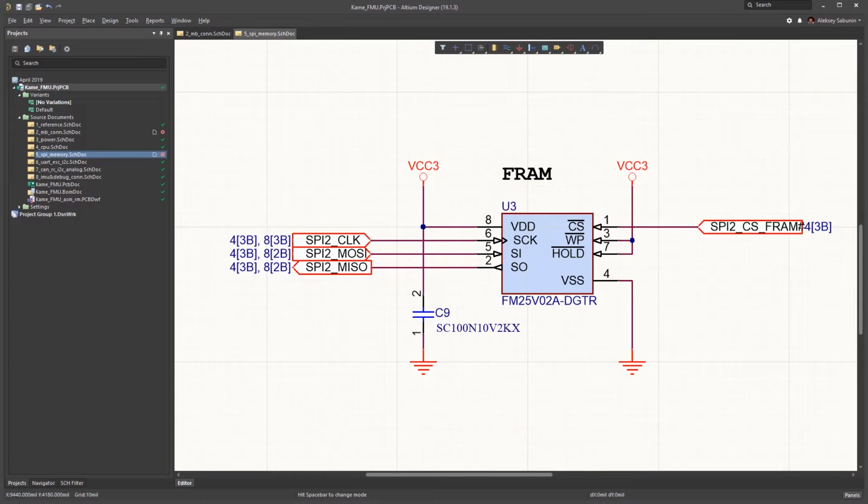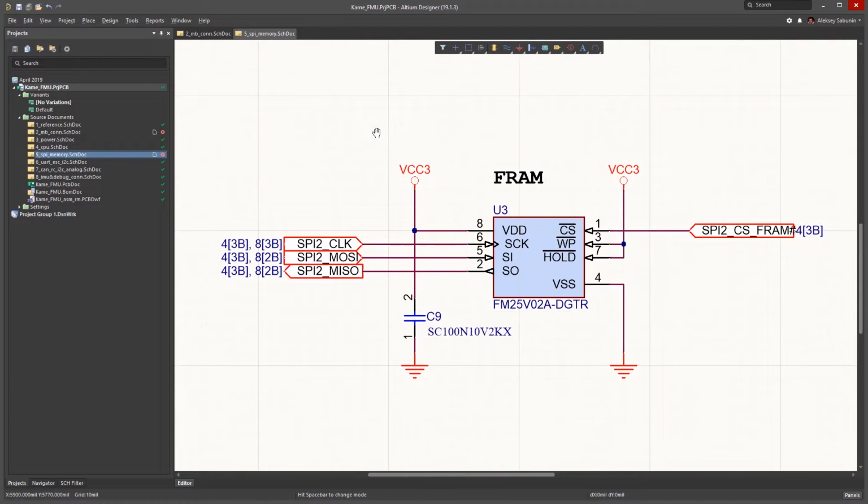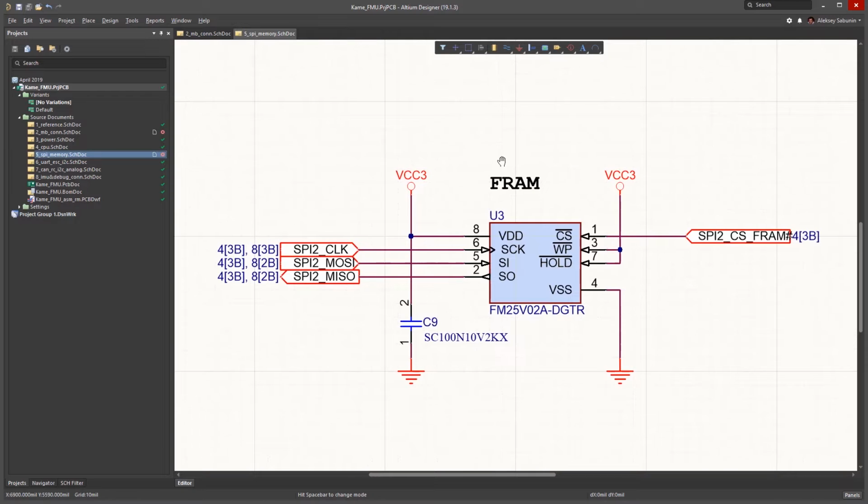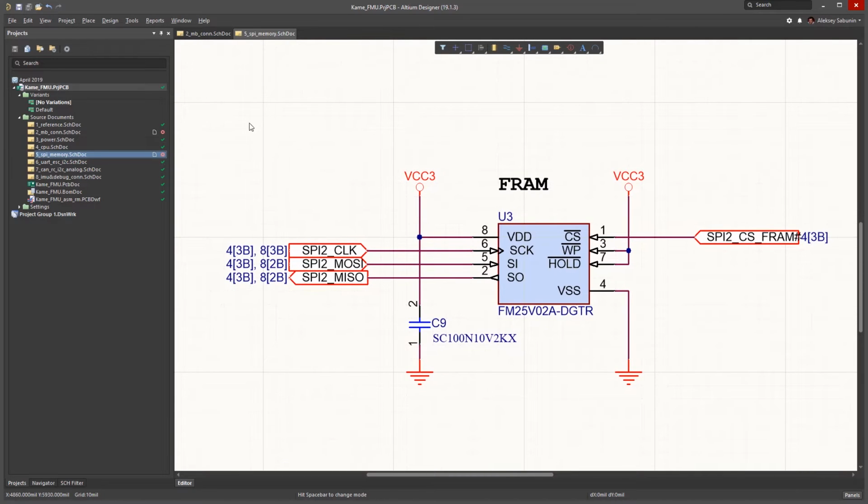In this video, you will see the practical benefits that Concord Pro brings to the standard user for part validation during the normal design process. This includes validation not only against the statuses within the local library, but also utilizing live information from global suppliers through Octopart, which provides distributor and manufacturer data. This can be done in multiple stages and places.